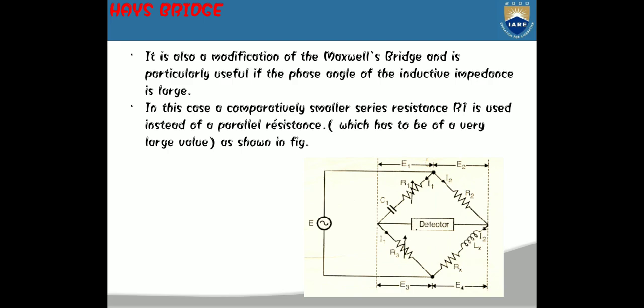To minimize mutual inductance, orient the inductors with their axes perpendicular to each other and separate them as far as is practical. Similarly, the nearby presence of electric motors, chokes and transformers, like that in the power supply for the bridge, may induce mutual inductance in the circuit components. So locate the circuit remotely from any of these.